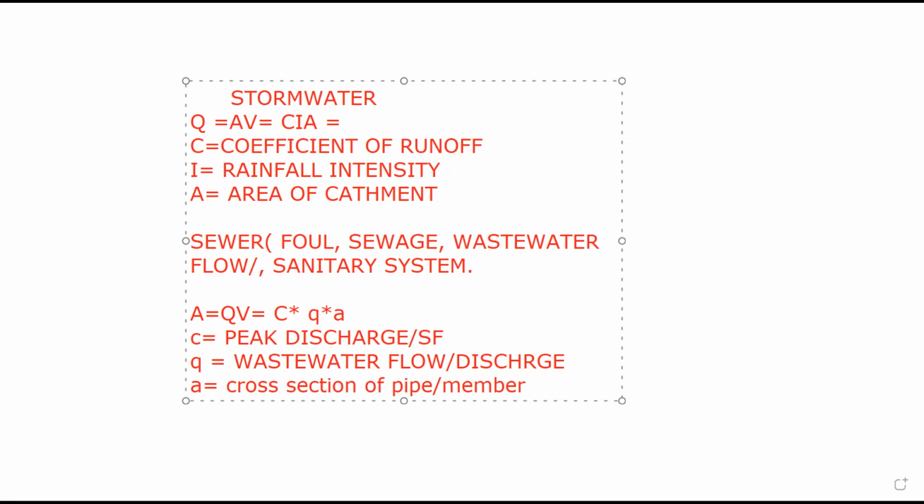No. So invariably, if I supply you 20 cubic meters of water and you use it in your house in a month, technically, I should expect you to produce wastewater that is worth 20 cubic meters of water. So that is simply where you get the value from. So you don't need to crack your head about it. So when we come to that place, we'll be using that individual water demand. That's individual water demand requirement. Right?